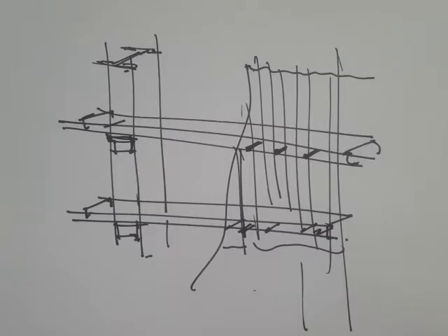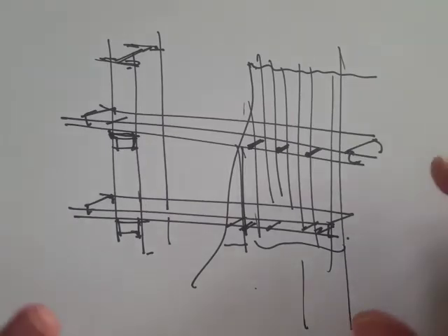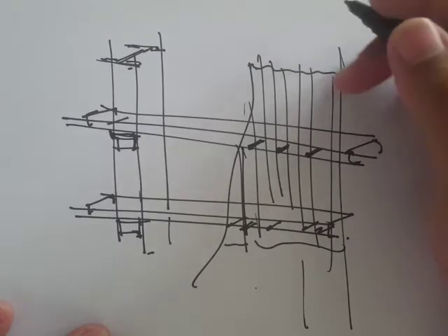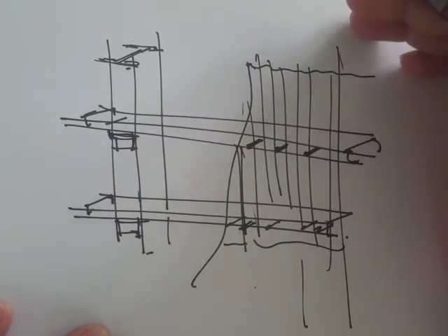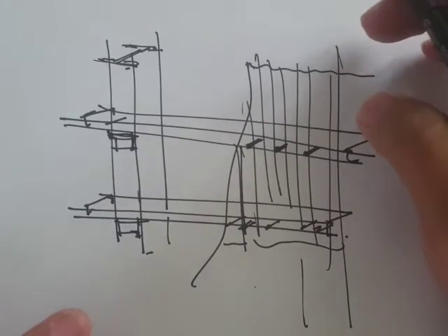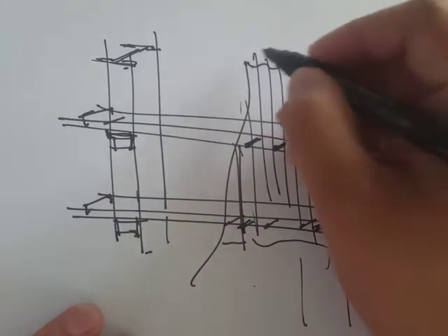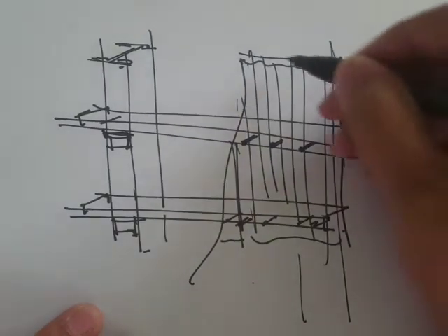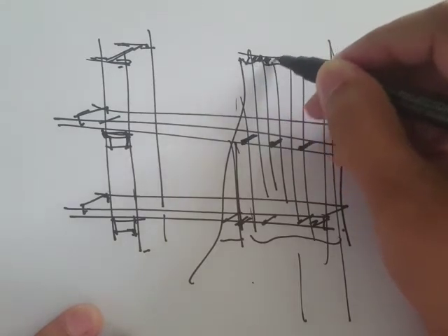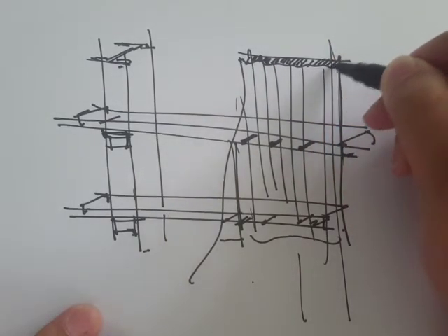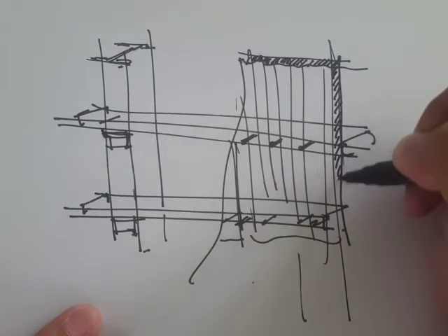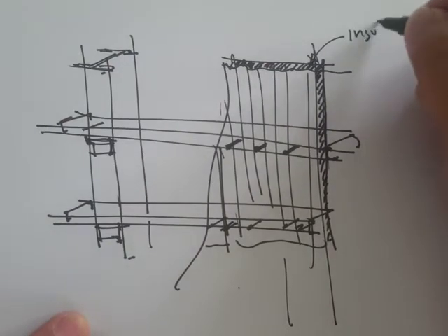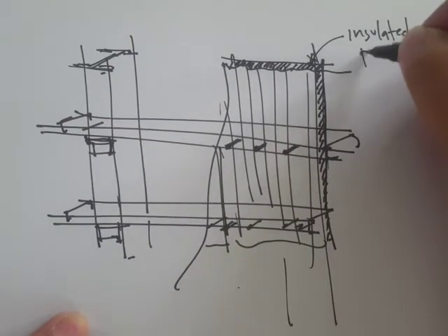Curtain sided. By the way, for example, for cold storage buildings wherein we need to maintain a low temperature inside the building, it is also necessary to include insulation materials. So for example, this is the wall cladding, which sandwiches the insulated materials or insulated panels. Okay, so that's also possible. Insulated panels.